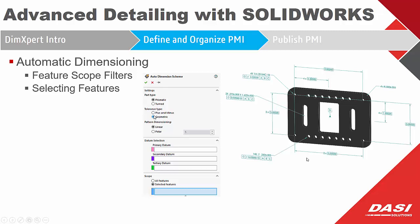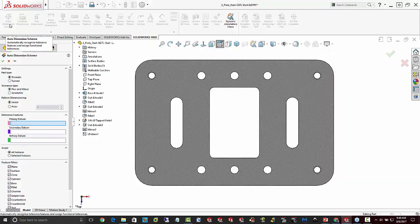and define all of the holes. In the previous example, I did everything in one step and then moved the annotations around. Here I'm just going to show you how to lay out and define the dimensions in two steps using the auto dimension tool. The first thing here is we want to make sure we use our prismatic, and we want to change this to geometric tolerancing.